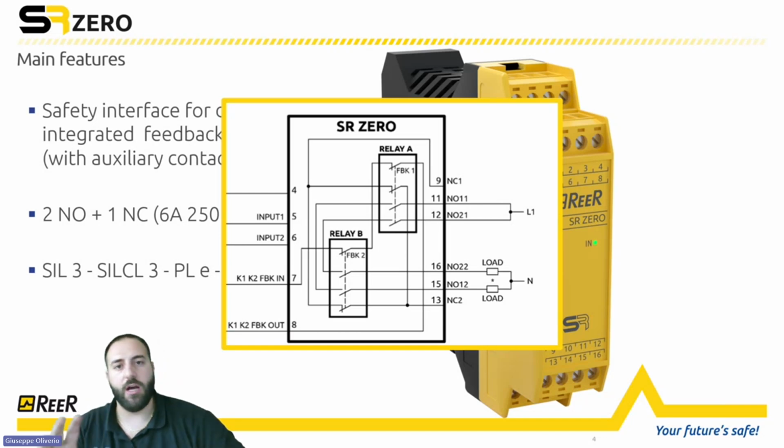So by using, for example, our light curtain, a type 4 light curtain plus the SR0, you can reach category 4. So you can mount it in an application that requires performance level E.